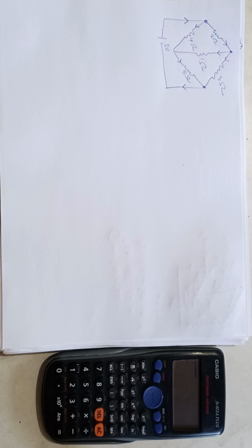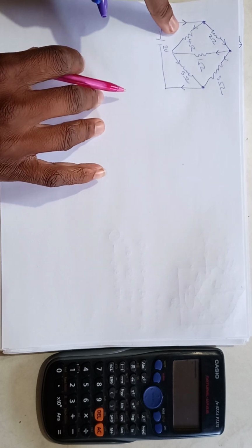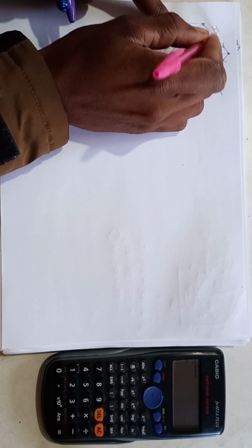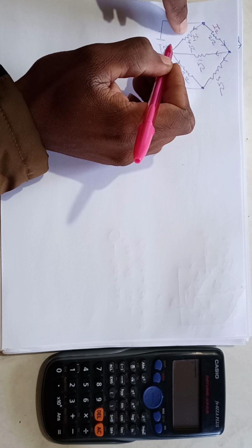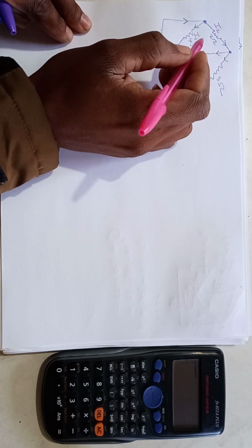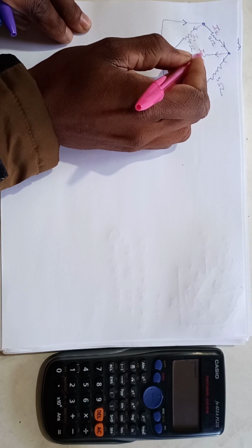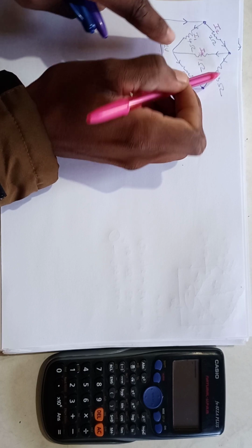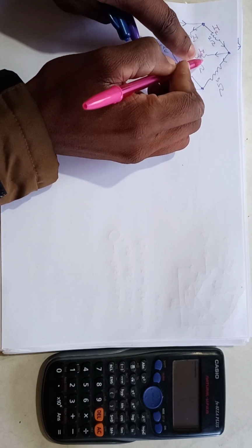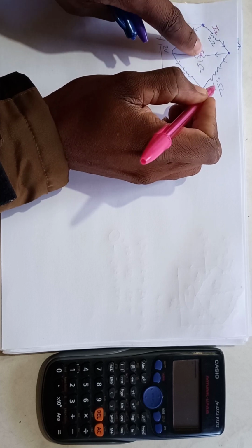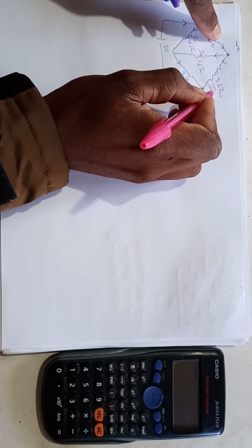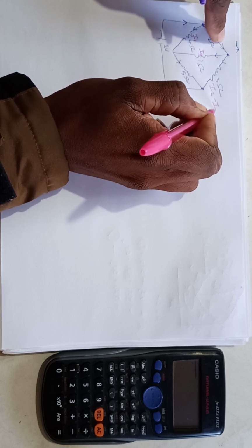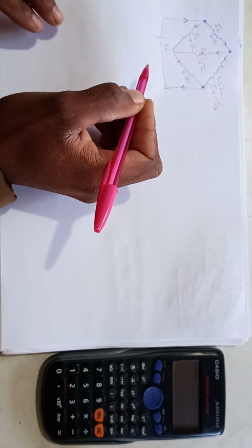Now what we need to do is to name our currents. So let's say the current here is I1 and the current there is I2. It doesn't matter, you can make this I2 and make that I1, but you must remember that this one, even this one, I wouldn't say you must make it I3. If you decide to make that one I3, then you should know that this one will be I2 minus I3. So since we made this one I3, then this one would be I2, the big current, minus I3, the current that split off that current.